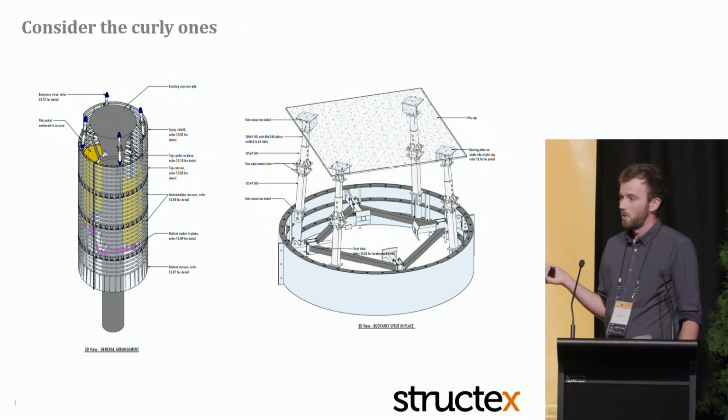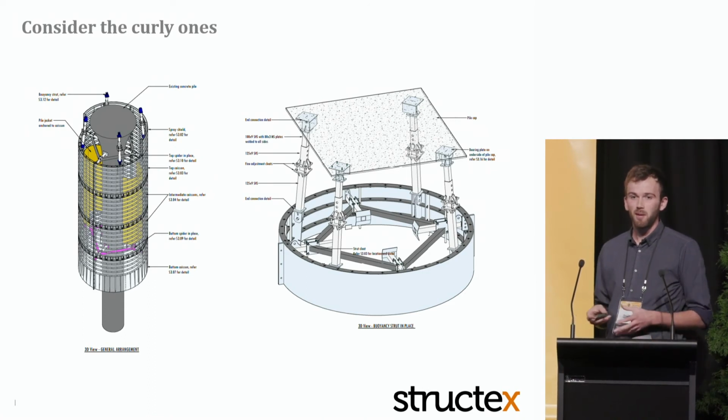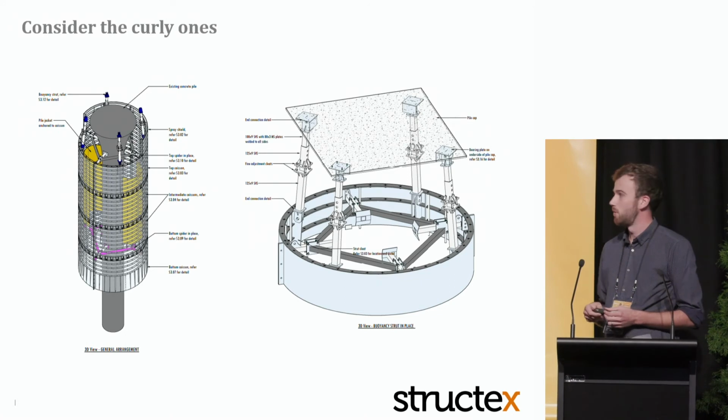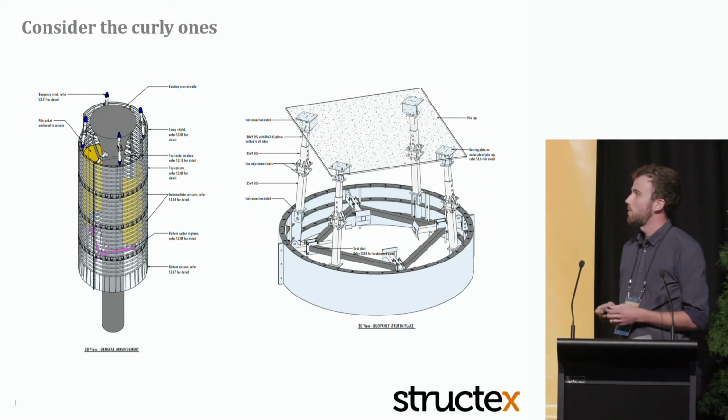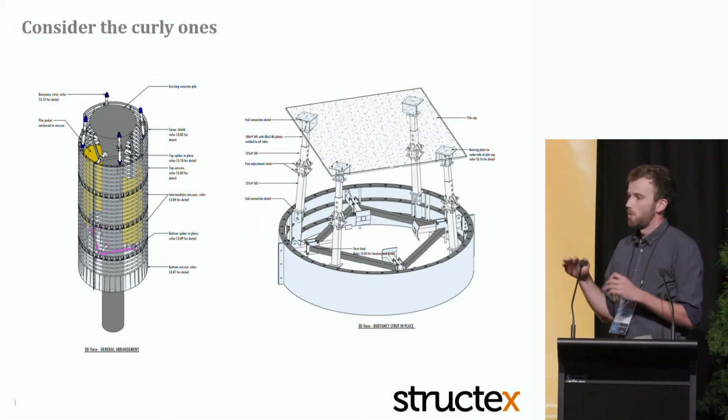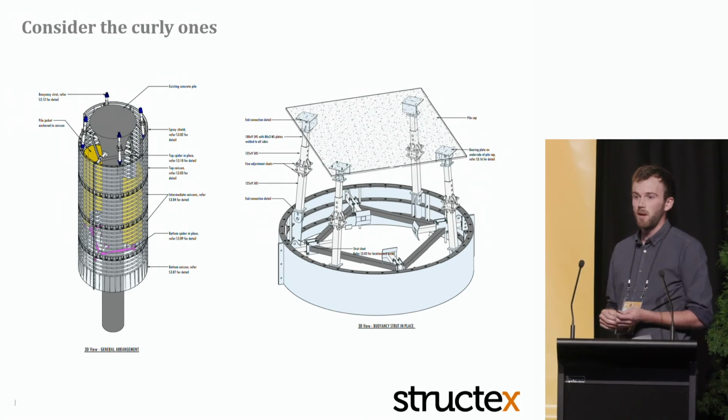If you have a large volume of water that you're displacing, you create quite a substantial buoyancy force. When our design team ran the numbers on this, it became clear that it was actually right on the edge of putting a net tension into the concrete piles. So not such a great thing for an asset that you're trying to retain. So setting some limitations around what the differential water levels could be, and how that protects the structure for the long term.